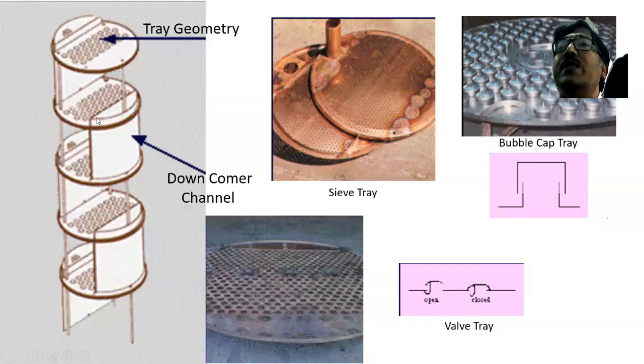And now I will be showing the distillation columns. The internals of the distillation columns have been shown. Now, one important thing I want to mention: distillation columns may be pack type columns or plate type columns. Both pack types and plate types, and nowadays hybrid columns are also there, can be used for chemical separation purposes. But for cryogenic distillation, generally plate columns are used.